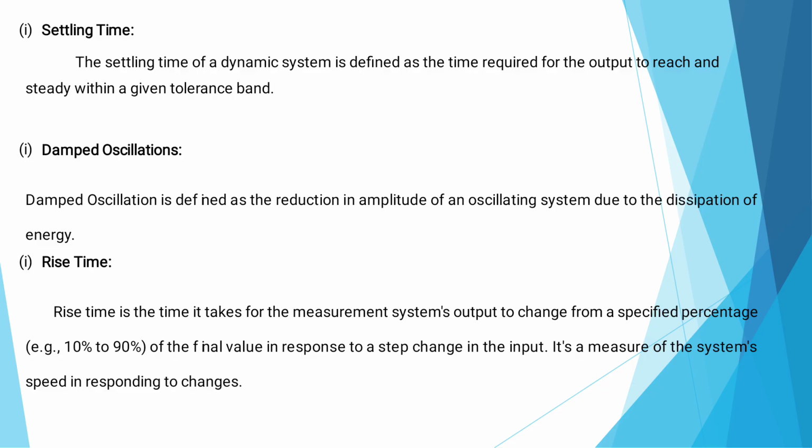In the case of rise time, it is the time taken by the output to increase from a lower percentage to a higher percentage of the final value, usually from 10% to 90%. It represents how quickly the sensor output rises after an input signal is applied. A smaller rise time means a faster sensor response. Rise time is also important in biomedical monitoring systems where rapid signal detection is necessary.